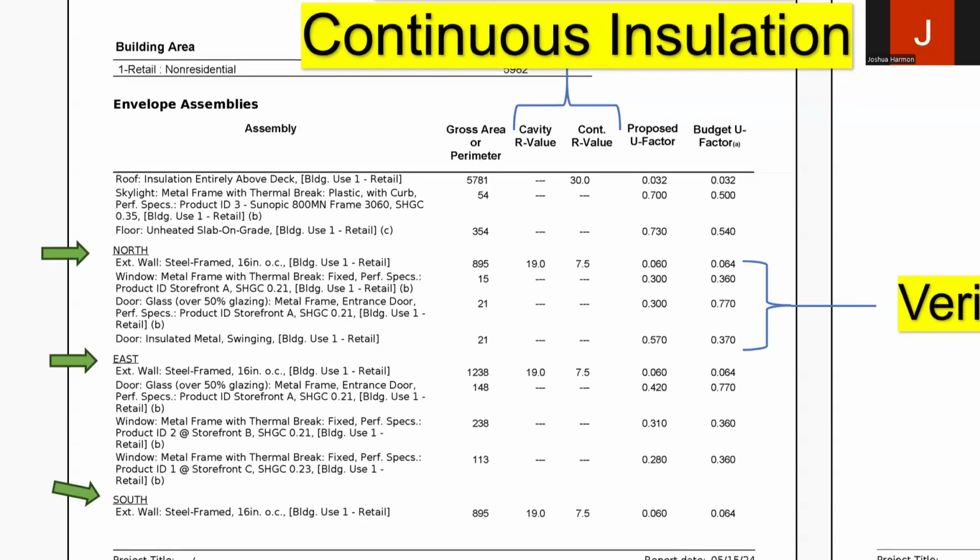Because I've done other things at other places. I've increased other values. I've added additional insulation, or changed expectations for the windows or doors, right? We'll have to add more insulation in one area to put less in another. And as long as the envelope passes, we're all good.